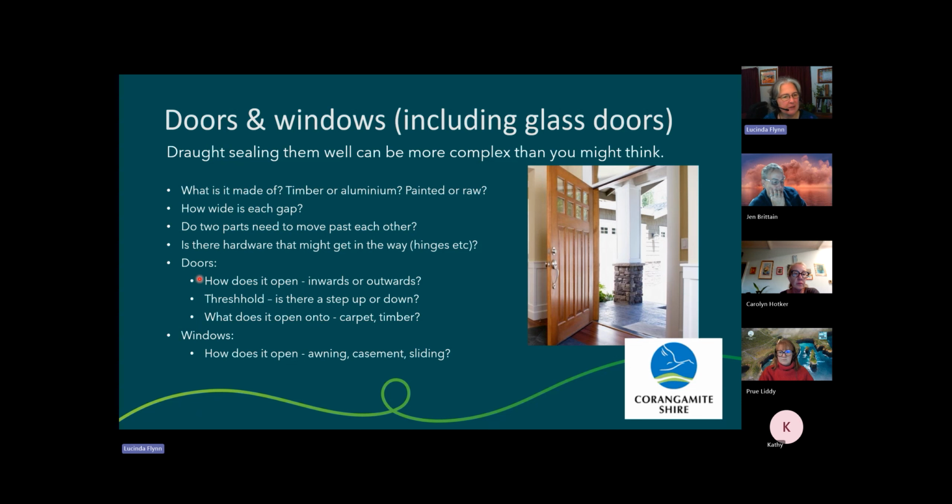You can have them, as I've listed here, how does it open? Is it in or out? Is there a step? Does it go up or down? What is it onto, carpet or timber? So there's a whole stack of things you need to know. And first of all, the idea would be to have a good look at it and see what you're going to need in order to get a seal around those areas.